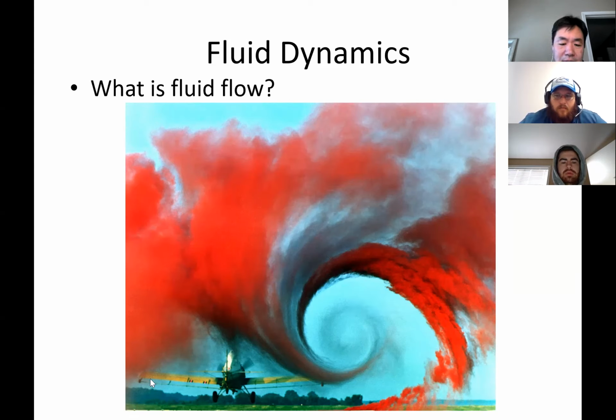Well, so imagine it's a 787, 747. It causes a lot of disturbance in the air. Strong vortices, just like a hurricane, right? Small scale hurricane, tornadoes, whatever. It's vortex. So then, if you are the small little one behind that jumbo jet, what happens? You're waiting in line to take off. There's the 787 in front of you. It takes off. Can you immediately take off? Probably you can, but maybe it's not safe, right? You have strong vortices behind the previous airplane. It's going to suck you into the vortex.